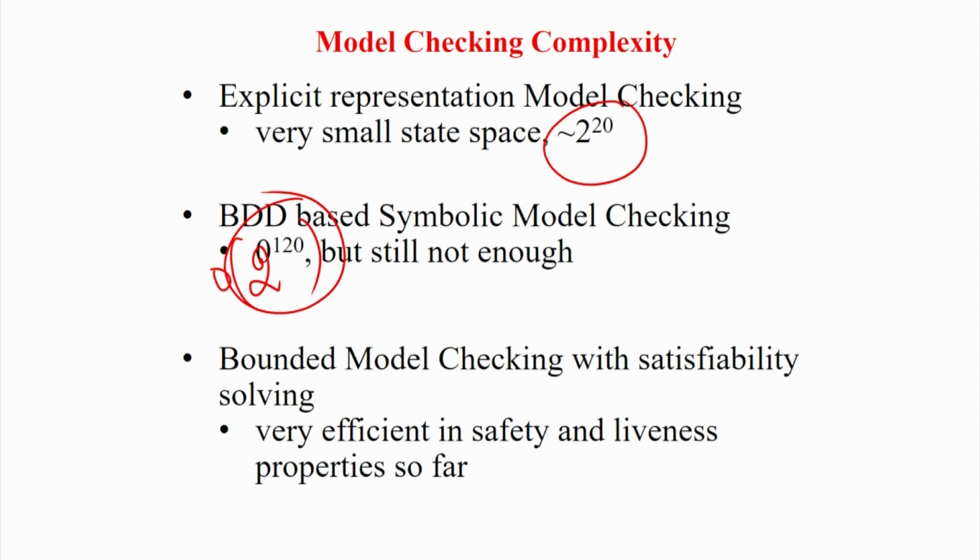So, what people try to do is modularize and go for distributed verification, and several other distributed techniques are available. Or somebody explicitly verifies all the blocks and then tries to see the interfaces, etc. There is another set of literature on how to handle such big systems. Another direction which we have seen in this work is that people have tried to model very big systems in terms of other types of decision diagrams, like high level decision diagrams or arithmetic decision diagrams, and try to formally verify on those high level BDDs. But again, model checking as smooth as what is available for bit level BDDs is not available for those high level diagrams. So, people are still thinking about it.